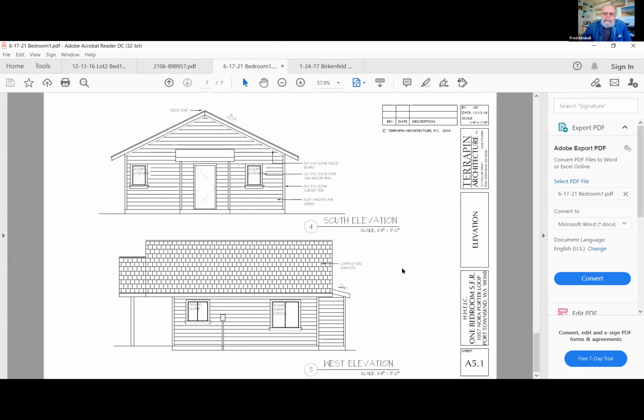And then these are submitted with your building permit, and you can probably expect some red lines from the building plan reviewer as to either questions or comments as to what may be omitted, any piece of information that you happen to leave out because you didn't think of it, or any information that they found not quite complete enough to feel comfortable issuing the permit. They'll generally come back with a little list of questions that you have to address.